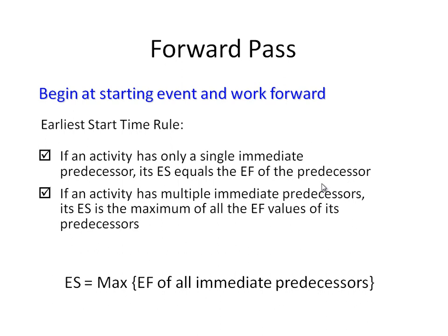I don't have to wait until Monday unless it's specified that you have to wait until the finish of Friday at 5 p.m. and then start Monday at 8 a.m. If that's specified, then that will be it. But we cannot start the successor without finishing the predecessor. So the early start for the successor is the early finish of the predecessor.